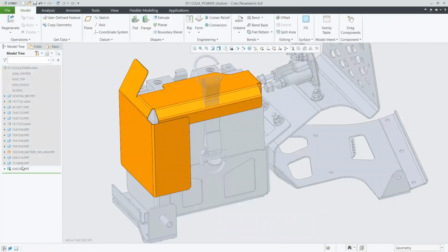So line these up, and right away you can see a few things going on. At the top there, there's an indentation that we're not accommodating for. And on the back side of this, there's a big strap that's just going directly through our bracket. So obviously these are two things. If we want to use this battery, we're going to need to make some changes.